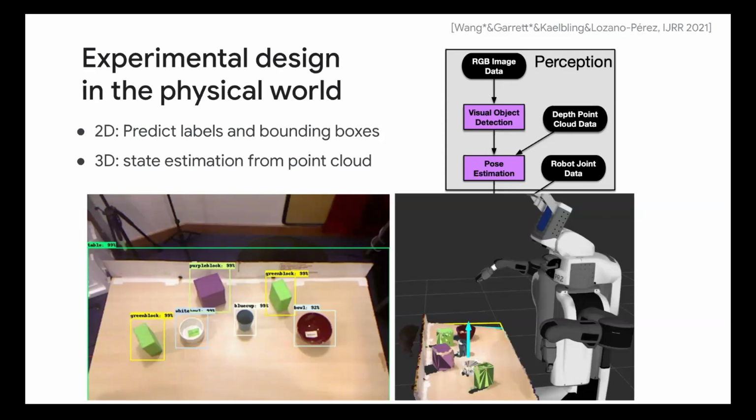Then we access the models corresponding to these specific objects and try to reconstruct them with the point cloud. All of this sounds pretty complicated, but the goal is really to reconstruct what the scene is in the robot's belief. Once we have that, we get the initial state, and we can use it to decide how to get to the goal.